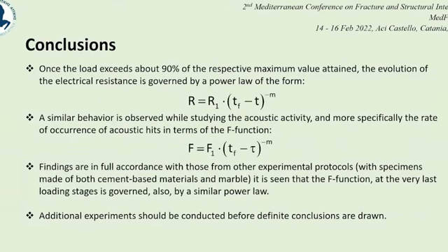In conclusion, what I've shown you so far is that for both cases of specimens, in the case of electrical resistance, a power law appears when the load exceeds 90%. A similar behavior is also observed for the F function. These findings are in full accordance with those from other experimental protocols, especially in cement-based materials and marble.